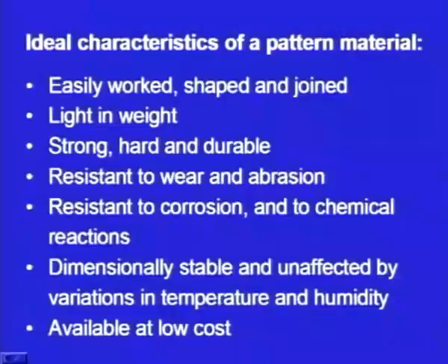It can't serve as a model for making several molds, whereas an ideal pattern material should have good resistance against wear and abrasion, and the pattern material should have good resistance against corrosion. This comes when we use metals and alloys as the pattern material.